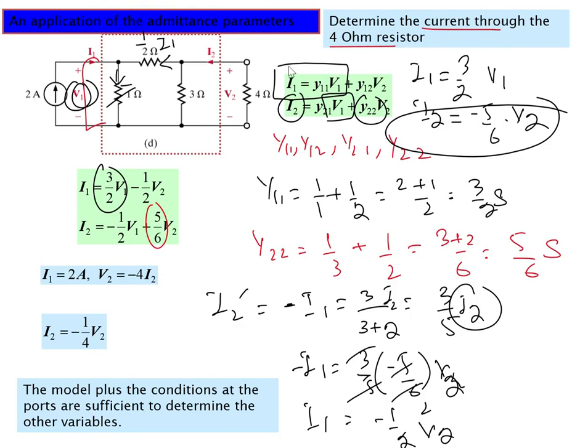So this thing is I1. Let me make this yellow. So this is I1 and this is I1, and this is V2 and this is V2. So this must be equal to y12. So we can say that y12 is equal to minus 1 by 2 of V2, which is here. Similarly you can calculate the other part by using the value of I2 as a branch current of I1 and then putting it in the value.